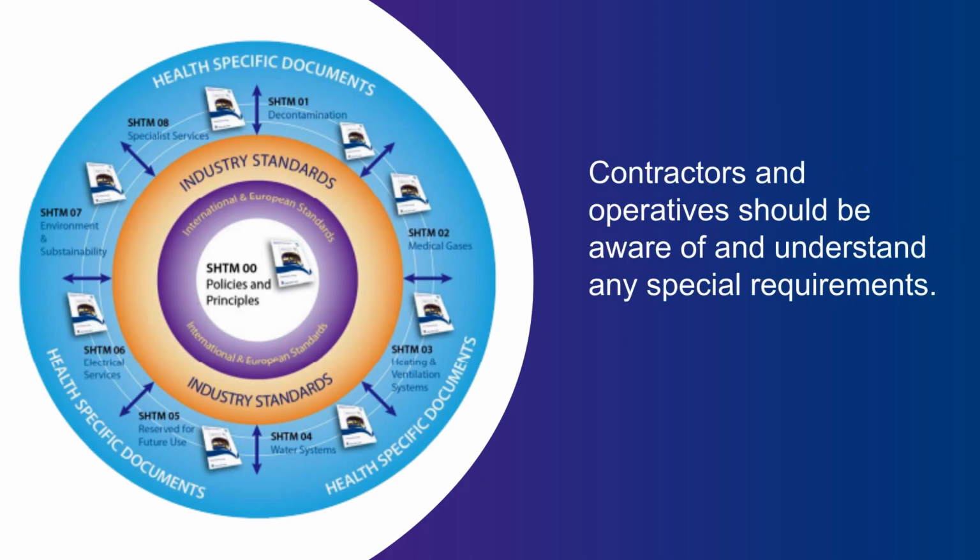Contractors and operatives should be aware of and understand any special requirements in the installation of ventilation, water, plumbing, drainage, and medical gas systems in the healthcare built environment. For example, some clinical rooms may require specialist ventilation, maintaining either positive or negative air pressure to prevent infection risk.